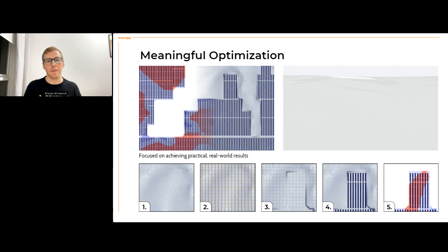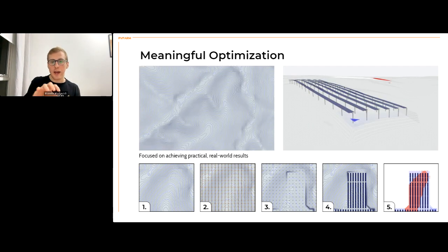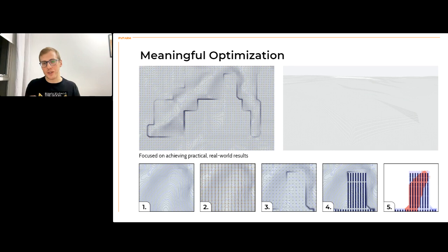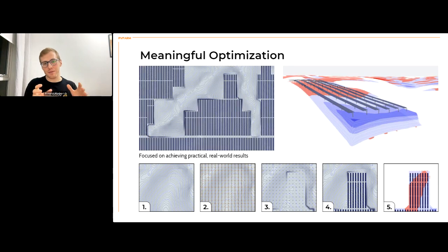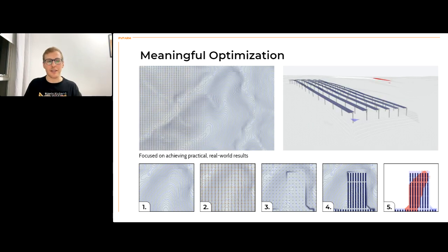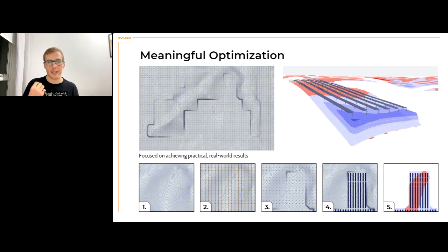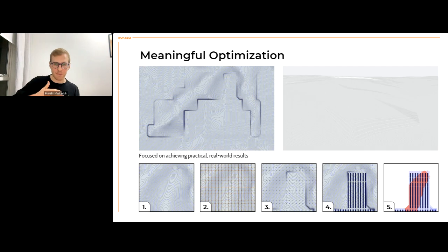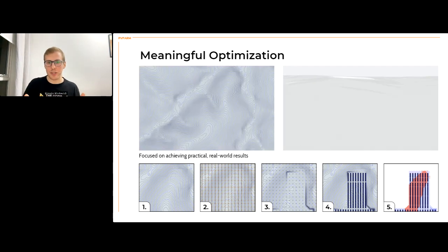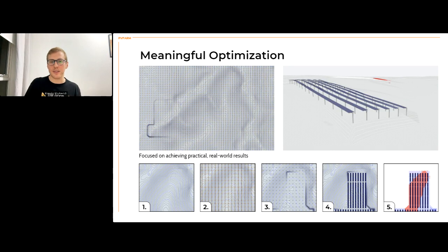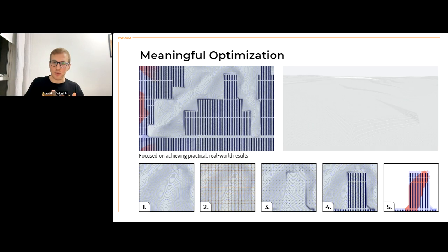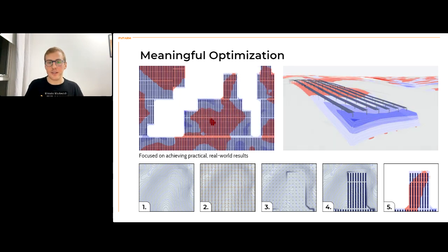And then when we run grading, we convert this grid into a kind of grading grid, and I would say enlarge it a little bit. The whole point of this enlargement is to mimic grader machine blade behavior, because we know the grading will be happening with a machine, and it has a certain blade size. So we enlarge the grid to run the efficient cut fill analysis.